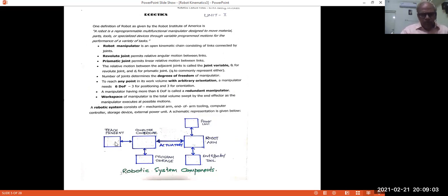But for continuous path control, like spray painting, etc., probably an expert will run the endpoint, the gripper, through the various motions. And then in the trajectory or the path, the times, the positions, and therefore the velocities of the joints are all recorded. And when the path is completed by the expert, later on it can just be put back into a proper code, and when it is run, the end effector will be doing just what the expert has done. That is one method of teaching.